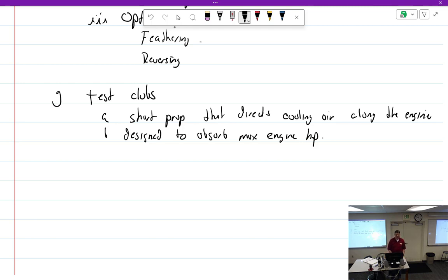What do you mean it was off? They made it so that one blade was like a half inch long, so it was all off center and shook the engine as it went around. Well, this helps counteract the P-factor. The one side of the blade has more thrust, so make that the shorter one. It was like the prop was symmetrical, but where they drilled the prop bolts was just off. Whoever built it, the prop shop. That's scary.